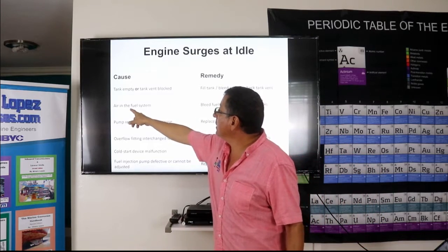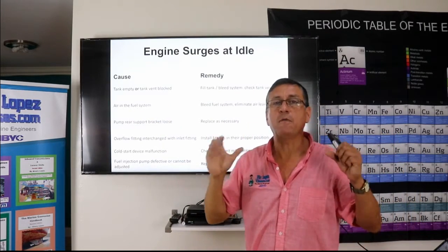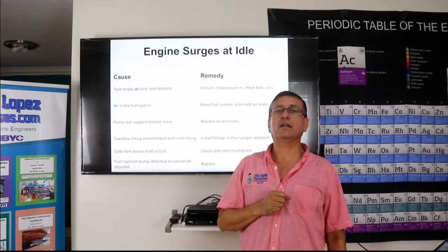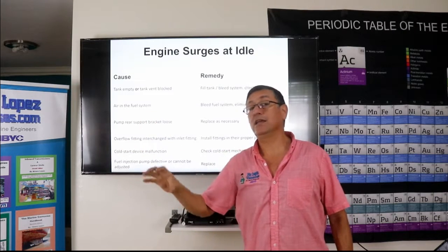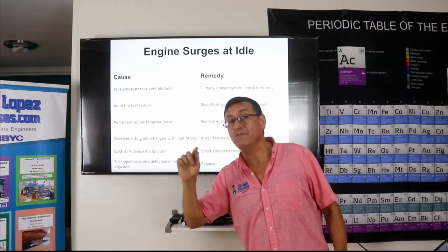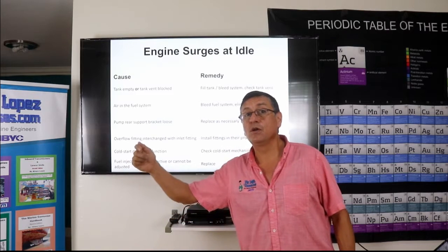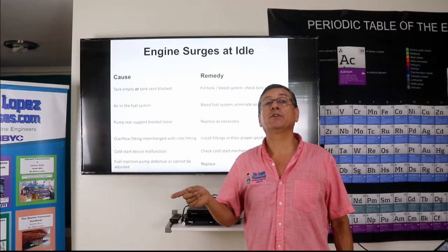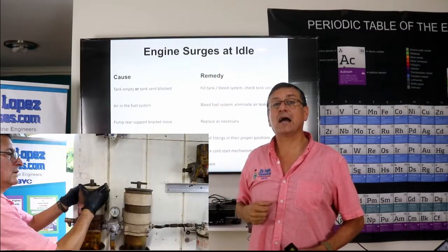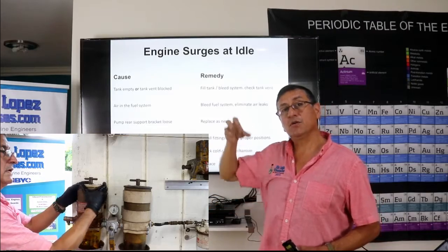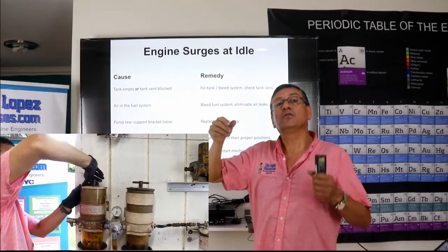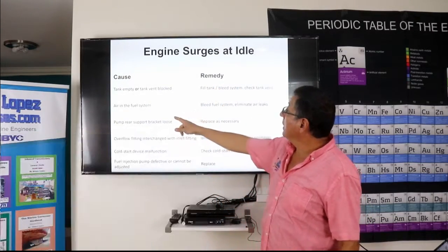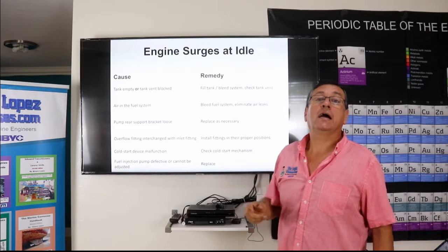The second one, air in the fuel system. Bubbles, foam. Air in the fuel system. What is the procedure? What is the first step when you have air in the fuel system? Check in the water separator filters if you have air in the fuel passing through the filters. If you have air over there, you remember what is the procedure? You open the cap, like the video that you have over there. You open the cap a little, you drain, you spill fuel with bubbles, and you tighten the cap again. Bleed the fuel system and eliminate the air.